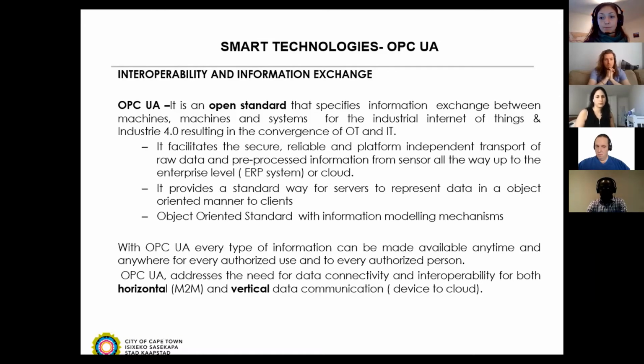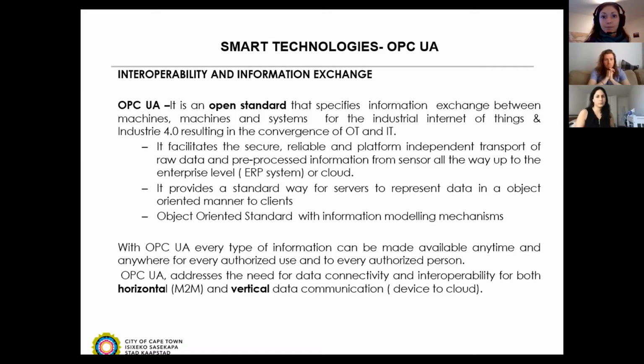And with OPC UA, we are targeting an environment where data can be shared across the organization without spending so much time trying to get different systems to talk to each other. You can have data in the automation environment shared with an ERP environment, for example, in terms of asset management. And also OPC UA enables you to move data vertically and horizontally.